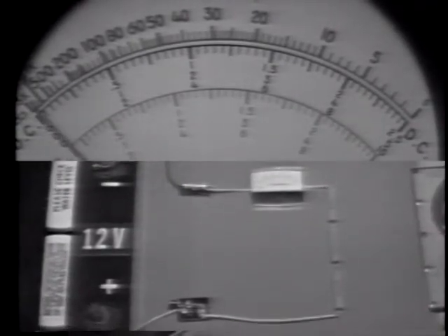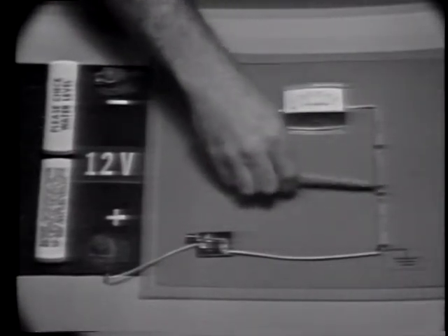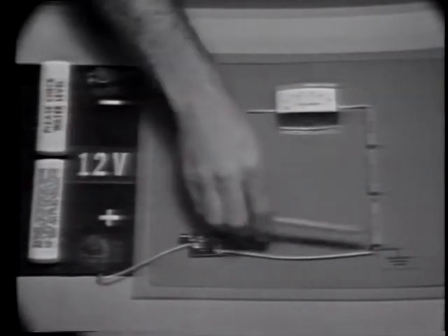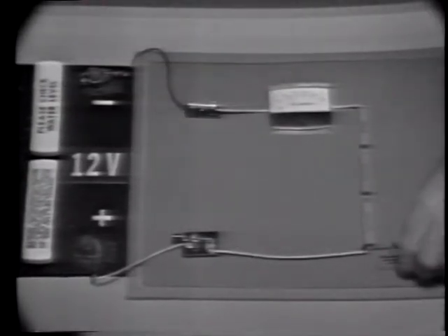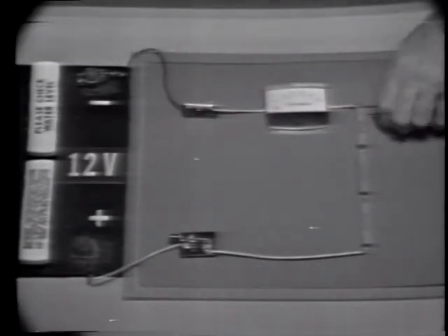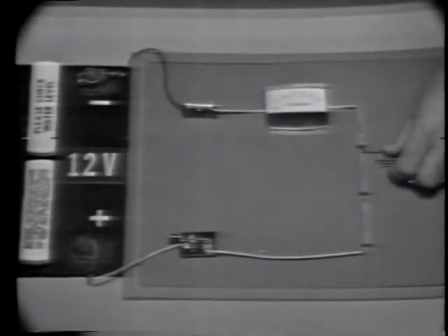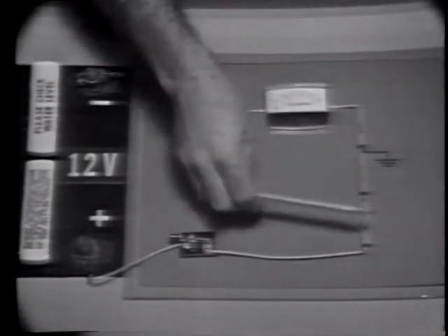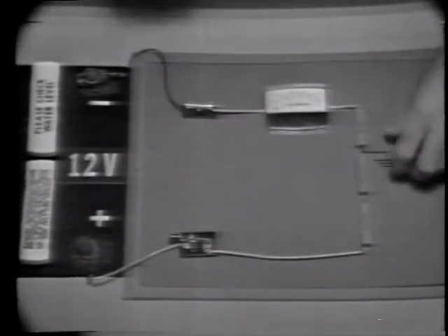We should also remember that different polarities can be obtained from a voltage divider. For example, if we were to ground the circuit here, all of the voltages in the divider would be negative with respect to this ground. If we move the ground up here, all of the voltages are positive with respect to ground. And if it's grounded anywhere in here, of course, we would obtain both negative and positive voltages. In this lesson, we won't be concerned with polarities, but keep in mind that different polarities are available.